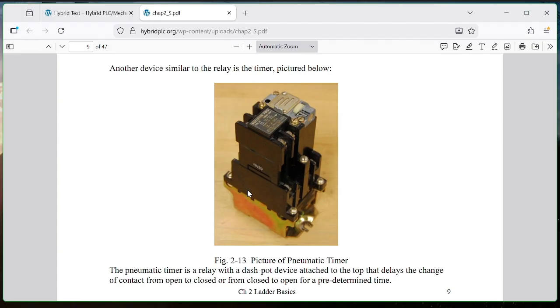And there's another bad side of this. There's an on-delay timer and there's an off-delay timer. And if you get the wrong one, you can't just flip a switch on this thing, you have to physically take the one off and put another one on. It's very painful. So again, there's a lot of reasons for using programmable controllers over these devices. You still find these devices in industry, however, because for some reason or another, somebody has been afraid to take this off and put a PLC on. So they still use the same device as they used before.